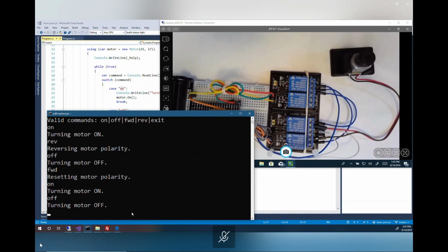and off. So that's a practical application beyond just turning a light on and off. We can actually turn physical things on and off. Motors, you could connect relays to lamps. These relays actually support up to 15 amps on a 110 volt circuit, so you could control your household lighting with one of these if you were so inclined.